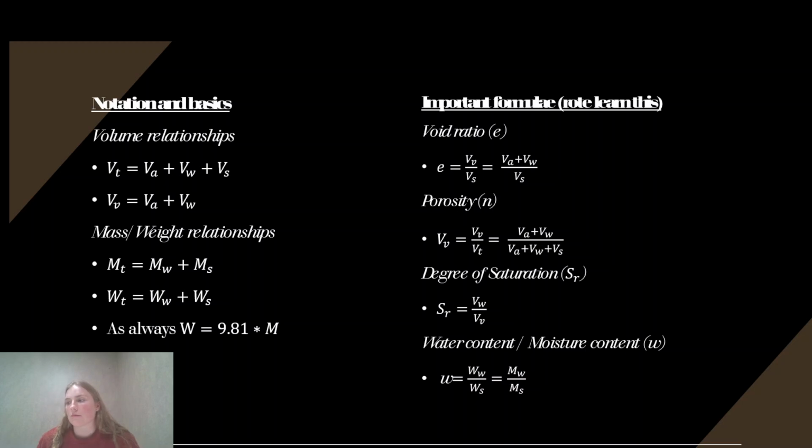Porosity only determines how porous a material is, the ratio of the volume of voids to the total volume of the sample. Just because this number is high or low doesn't mean a soil is permeable or not. Permeability requires all the pores, which is porosity, to be connected in a way for either air or water to flow through. So it's not the same, and you can have, for example, a high porosity with a low permeability if the voids aren't actually connected.